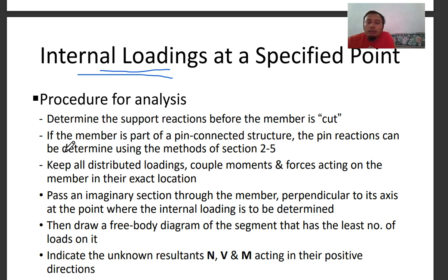The first thing, number one, is to determine the support reactions before the member is cut. So if it is a whole frame like this and being supported at these two points, you need to find the reactions first. Then only you can cut the section.